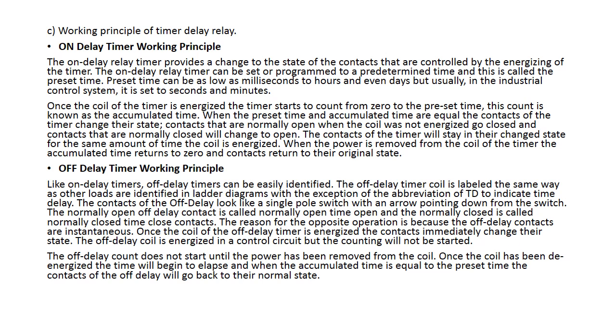So the contact will be normally open when the coil is not energized, and the contact of the timer will stay in the changed state for the same amount of time that the coil is energized. So when the power is removed from the coil, the timer accumulated time returns to 0 and the contact returns to the original state.